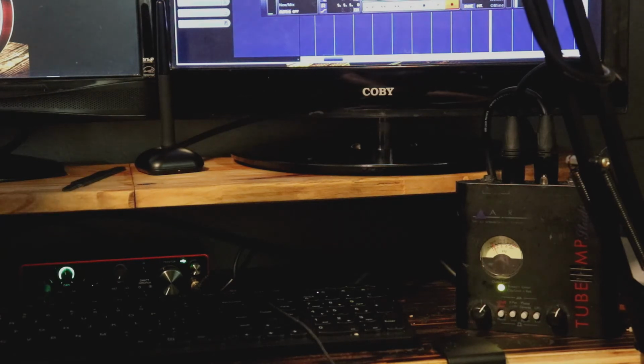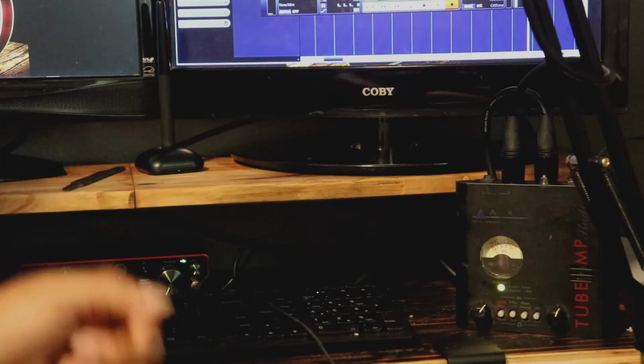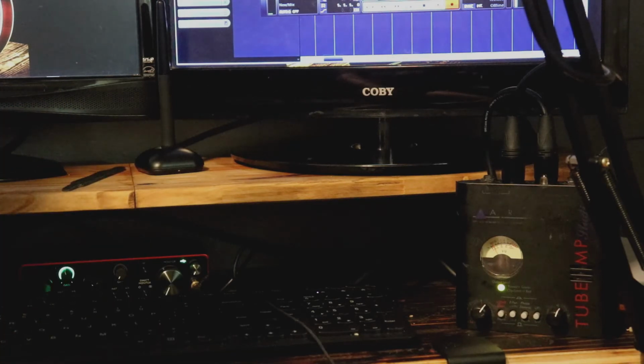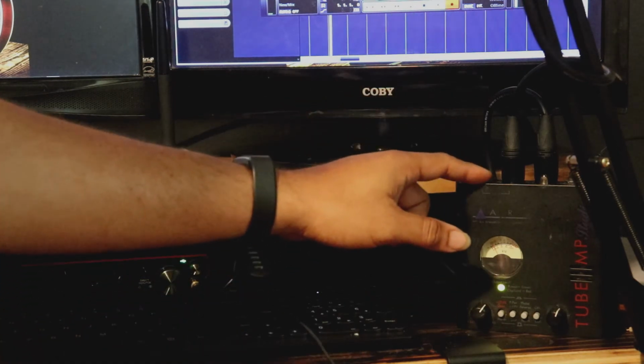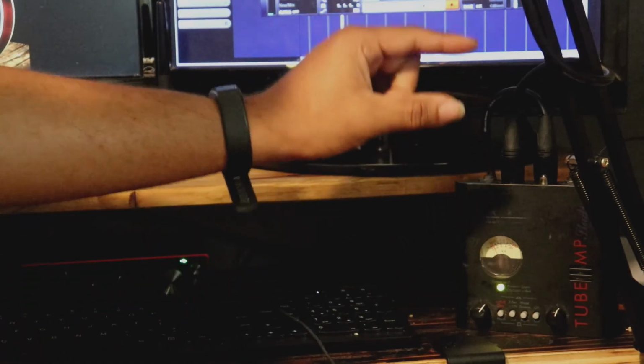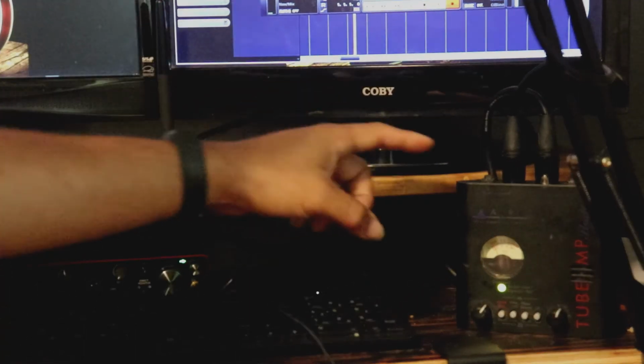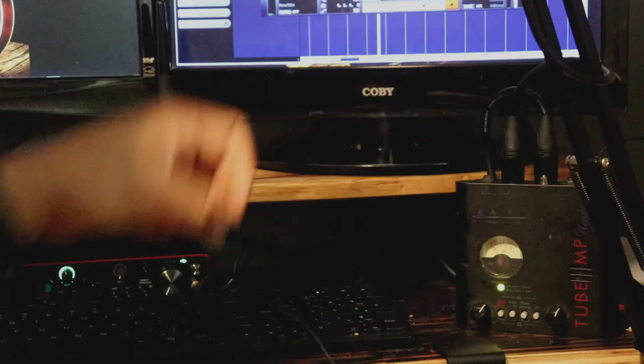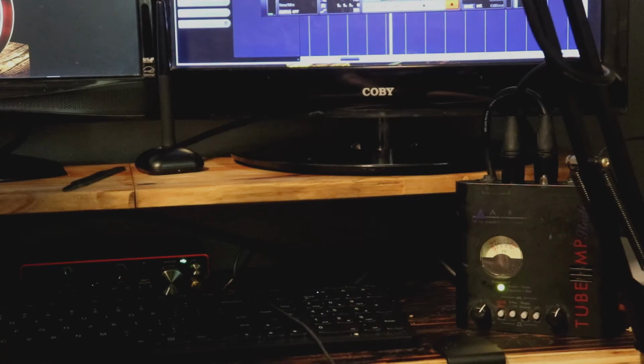I'm using a phantom-powered mic, as it's a condenser mic. Because of that, it needs 48 volts at the input. That means I cannot put a preamp in front of the input of this ART audio preamp. I won't be able to do that unless I make the EQ with the capabilities of having its own phantom